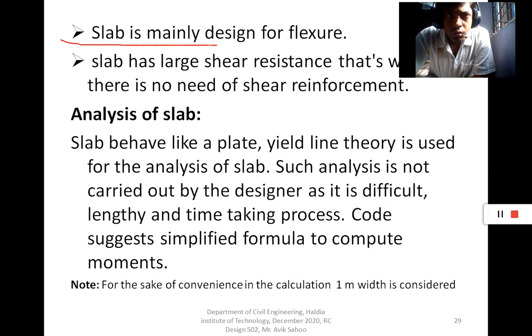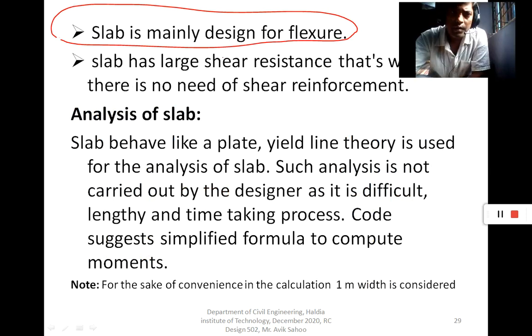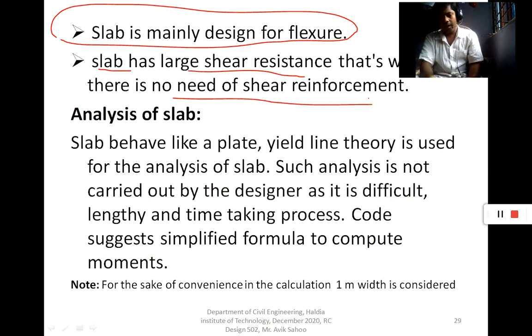Next, another point you note is that the slab is mainly designed for flexure. You know that the beam is designed for flexure as well as shear forces, but the slab, because the load is transferred to the support primarily by flexure, is mainly designed for flexure.